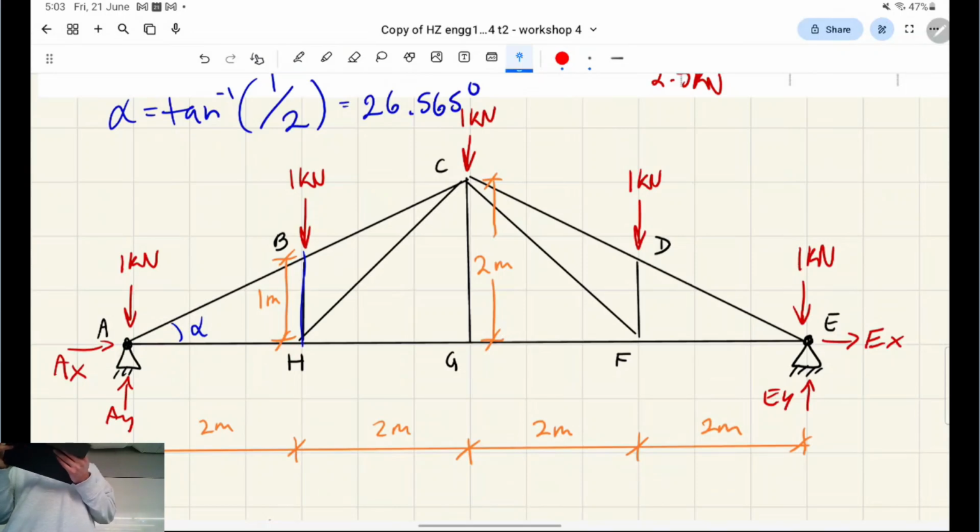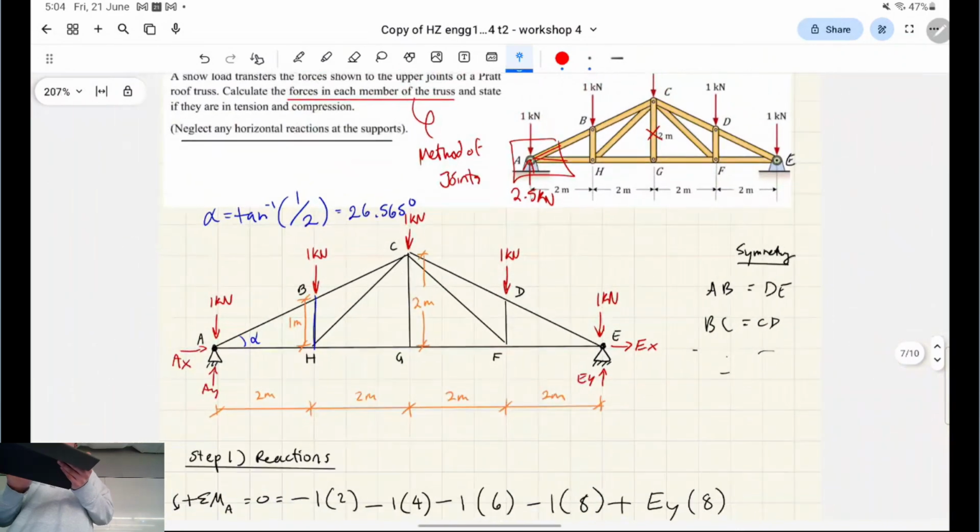Less members of that. Very good. So the fact that there's less members will be a good hint that there's going to be less unknowns as well, and therefore, you'll have enough information to solve it at that joint. So we're going to move from A to B, not A to H. Otherwise, you're going to get stuck. Too many unknowns, right?